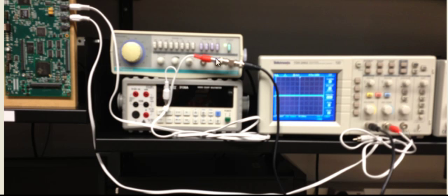At the same time, in order to be able to see the input that we fed to the board, the input is tapped and is connected to the channel 1 of the oscilloscope. So channel 1 is monitoring the input, channel 2 is monitoring the output, and when you change the frequency, you have these keys to go to different frequency, from low frequency to high frequency. So when you change the knob and you switch to 10K, 100K, 1 megahertz, you shouldn't be able to see much of a signal when you go to the high frequency.